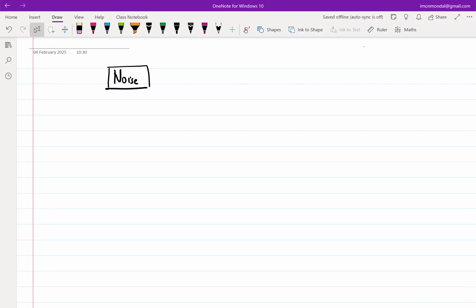So those are the things that we motivated and looked into. In the previous lecture, we talked about 2 receiver architectures which are commonly used in the literature. One is the 0 IF receiver, or 0 DC receiver, or a homodyne receiver. The other one is the non-zero IF or super heterodyne receiver. So we also talked about some of the benefits. The 0 IF receiver obviously has the benefit that its architecture is very simple. You just have an LNA, a mixer which down converts, and a low pass filter, and you are done.